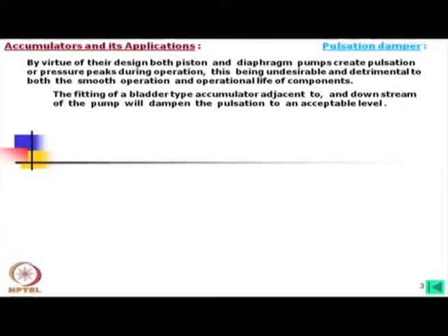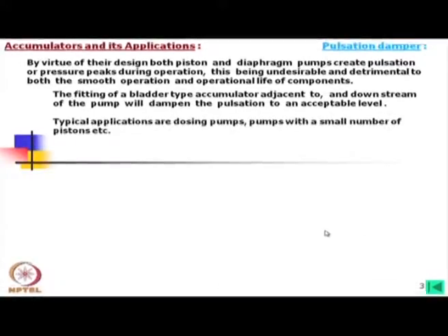In fact, the bladder initially will remain inflated, and then gradually its size will reduce and the oil will be stored inside. However, it is also possible that gas and oil are in contact, and no bladder is used. In any case, the fitting of a bladder type accumulator adjacent to and downstream of the pump will dampen the pulsation to an acceptable level.